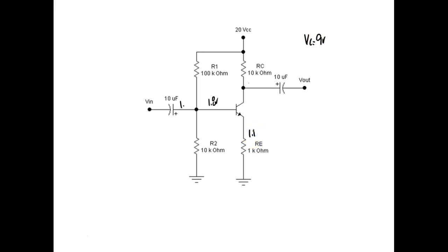So let's bring in a real small signal on this. We can't subtract too much from this. We've got 1.8 volts, we can add to or subtract. We can go up, but we can't go down below 0.8 or we'd cut the transistor off. So let's say I bring in an input signal that's 1 volt peak to peak. That'd be 500 millivolts up and 500 millivolts down. If I subtract from the 1.8 and it gives me less than 0.7 of a volt, the transistor's going to cut off. Okay.